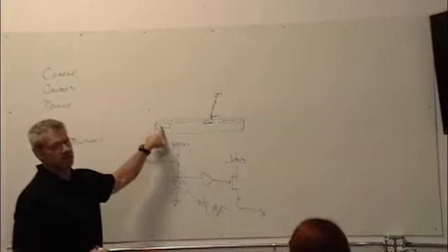So 0.7 divided by 150,000, and you're talking a couple of microvolts per electron. Which you got to imagine is way down your noise floor, which is one of the really nice things about a CCD device. Really, really low noise. Especially once they start figuring out what some of the problems were with them and doing things to fix those.